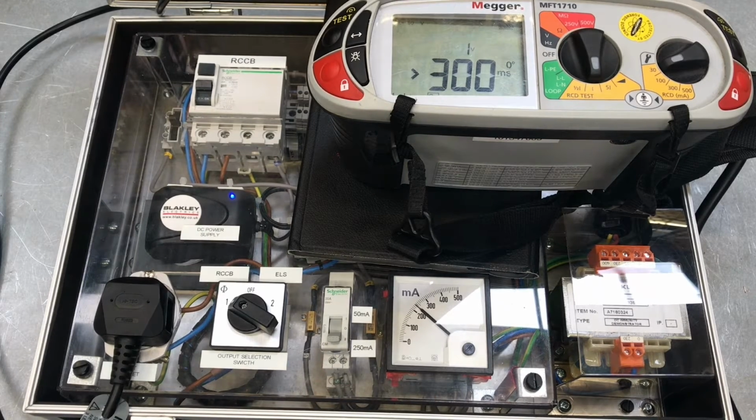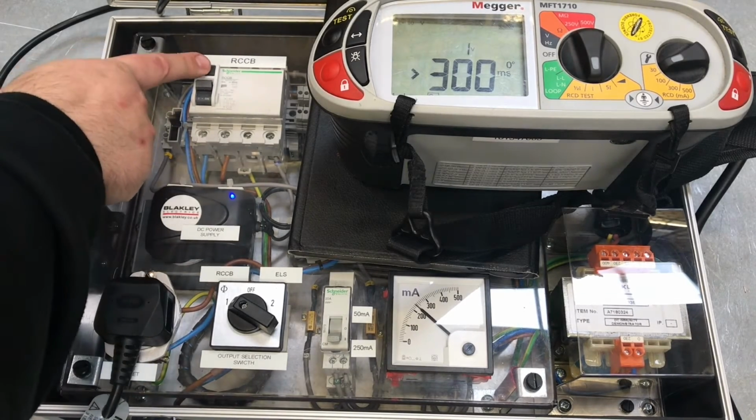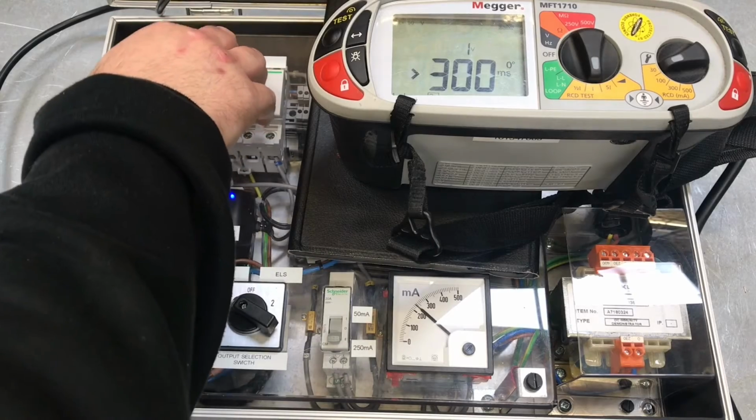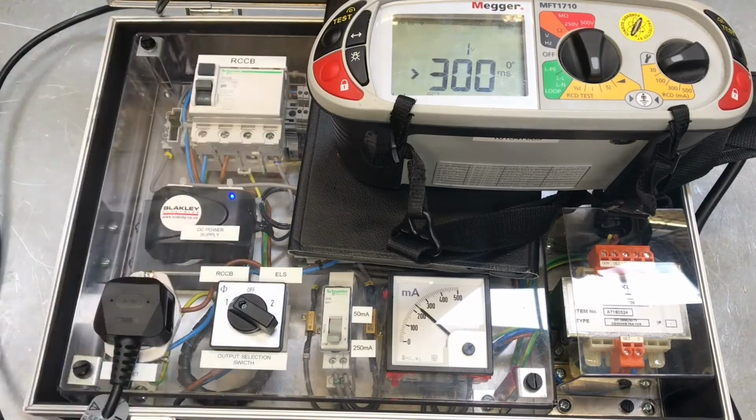How do I solve the mystery? I know what I'll do. There's a problem with the RCD. I'll push the trip button. That's what I'll do. So I'll push the trip button. No, it's not working. Bugger. So okay, the trip button does not work. It's saturated with DC. So I've got a problem.